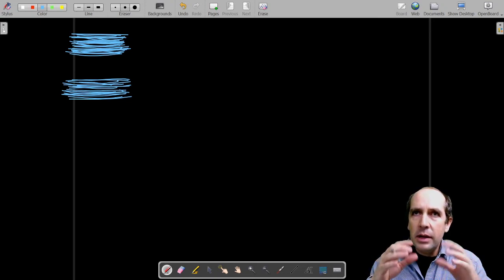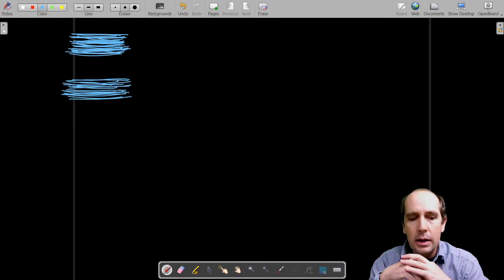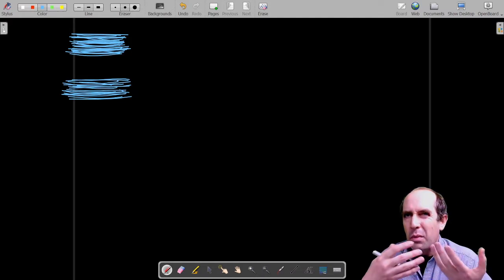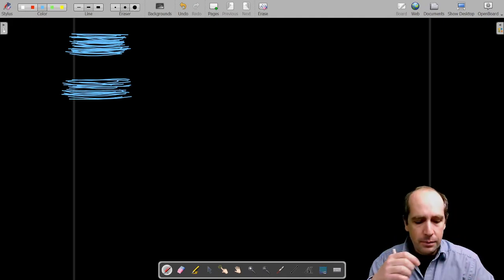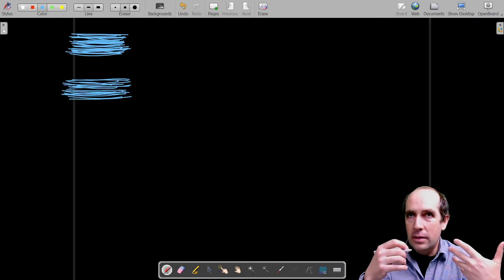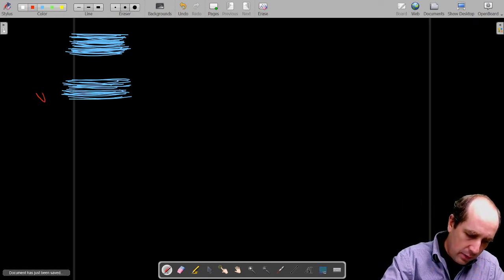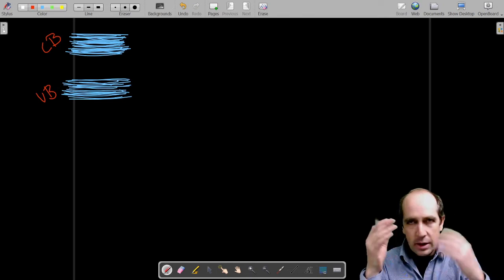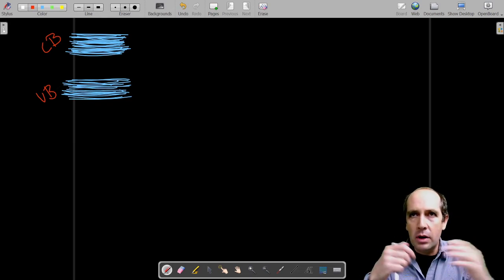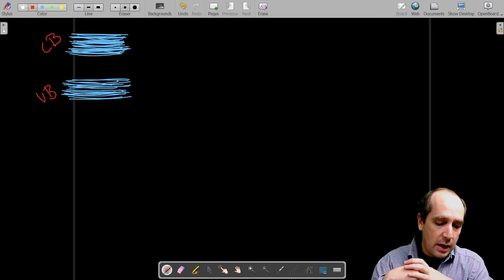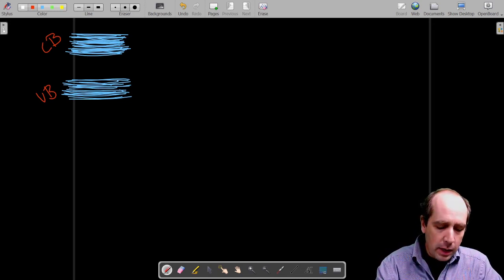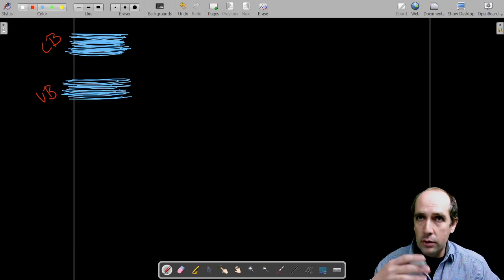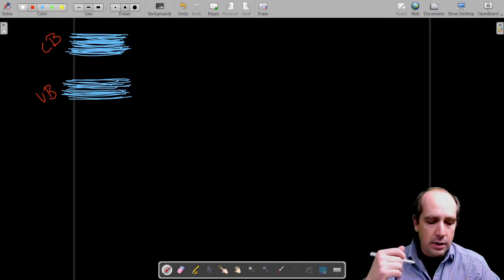It really is a material that has a completely full valence band, a completely empty conduction band, and a band gap, and therefore what we have is formally something more like an insulator. What I drew there are the bands, the valence band and the conduction band. Thinking again in terms of a semiconductor, the Fermi level, or the Fermi energy, will be somewhere in between the two bands, and essentially what we will see is that all the states in the lower band that I drew there are populated, so they are occupied, and all the states in the upper band, the conduction band, are empty.